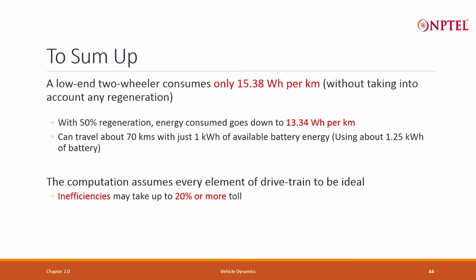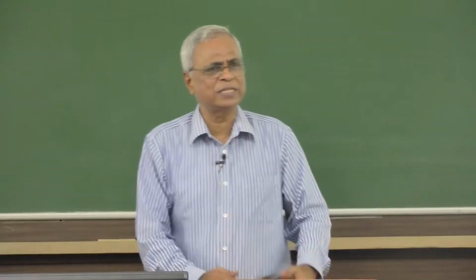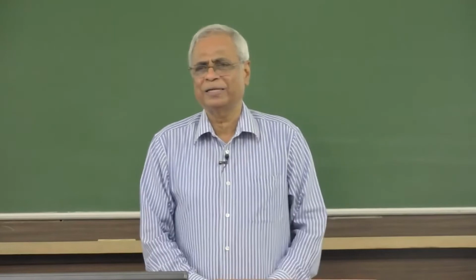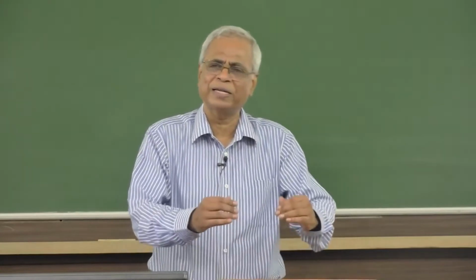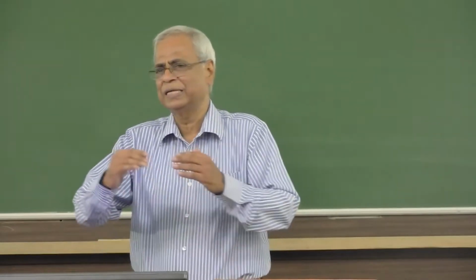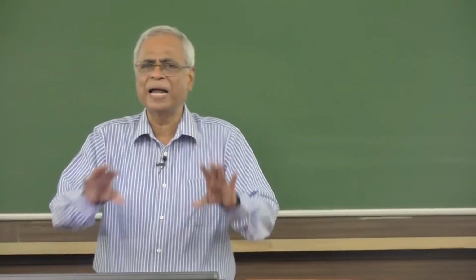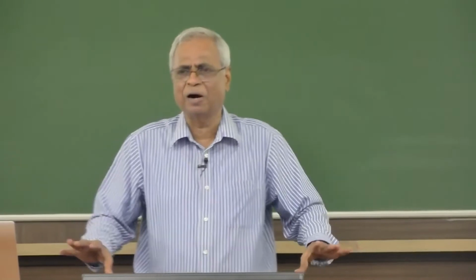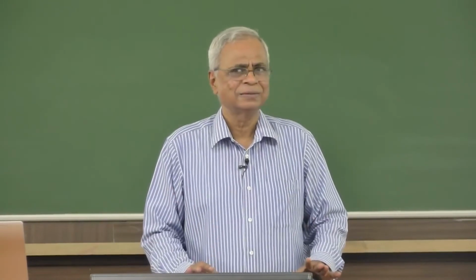All right. This is something that we did for the two-wheeler. So, we essentially have got the hang of it. Why did we do individual forces? Why did we look at the total traction force? Why did we look at the total torque, the total power and energy? Now, combined with a drive cycle, we are able to figure out what it takes, what is the energy that it takes.